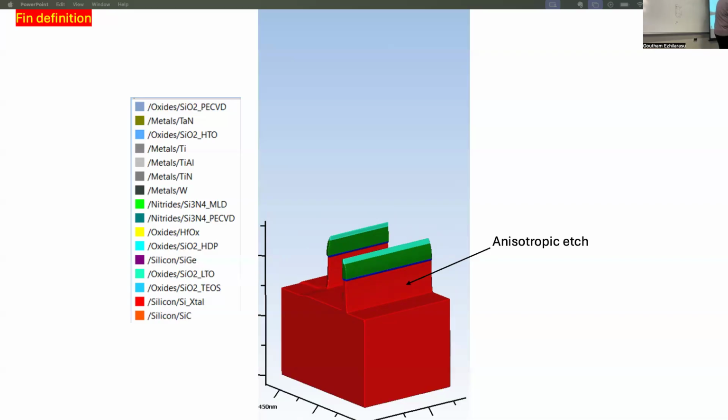That was like 3 to 4 etch steps that you just did: the nitride, pad oxide, and silicon. There'll be 3 different etches, because oxide will be one etch, nitride will be one etch, and silicon will be another etch. So now you have etched down and created this fin for your NMOS device, and that fin for your PMOS device.